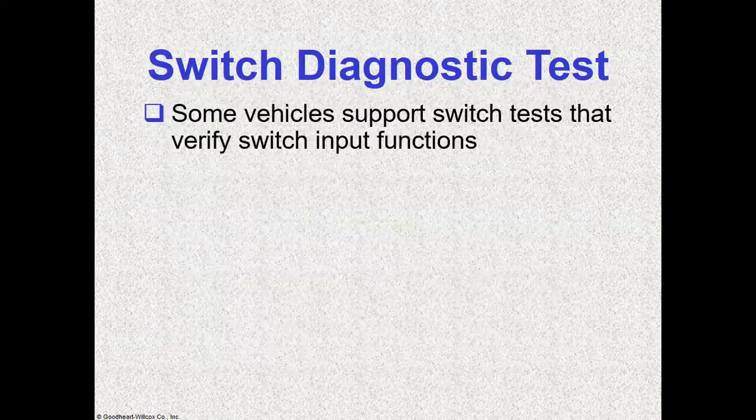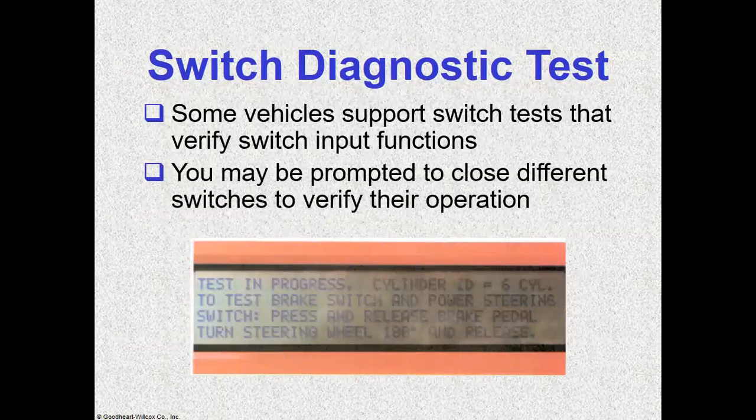We have switch diagnostic tests. Some vehicles support a switch test that verifies switch input function. You may be prompted to close different switches to verify their operation.